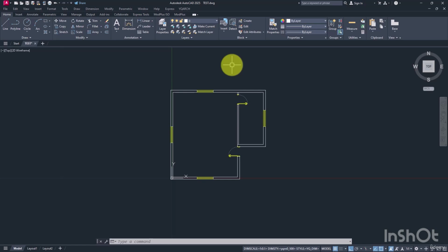They include some specific commands about modeling some geometries that we got no access to in the general AutoCAD, and they are dedicated that if we want to import those files, Revit would recognize them as proxy graphics files. So you may see some error messages while importing these files because the file contains proxy graphics.